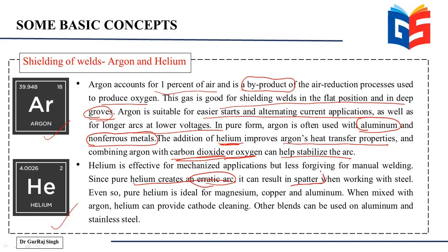All those who are studying welding should be aware of the term spatter, which basically means that whenever we are trying to perform a weld, the welding rod is moving in this direction, there are loads of droplets of molten metal which are being spilled out in form of these droplets around the weld pool. So it is called spatter, and this gives a very poor surface finish to the overall part when you take a look at it after the welding has been completed.